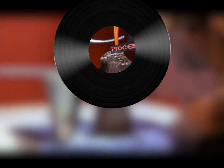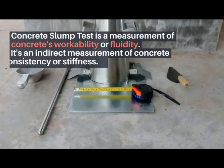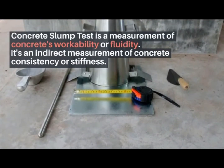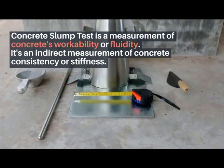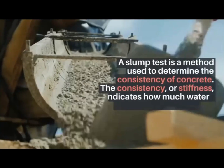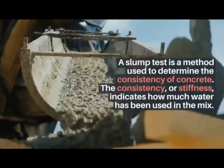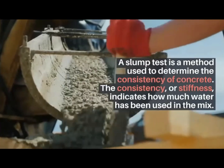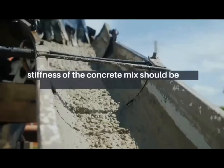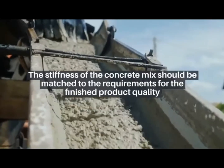For you to test the workability of concrete, there's a test called the slump test, with its applications and types of slump. The concrete slump test is a measurement of concrete's workability or fluidity. It's an indirect measurement of concrete consistency or stiffness. A slump test is a method used to determine the consistency of concrete. The consistency, or stiffness, indicates how much water has been used in the mix. The stiffness of the concrete mix should be matched to the requirements for the finished product quality.